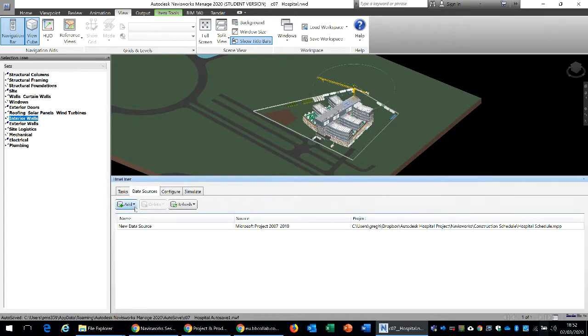So you could bring the bar chart or your plan, which is developed in dedicated scheduling software, within this environment. Your plan could have been developed in Primavera or Microsoft Project, or you could use any other scheduling software, and then you can export your plan into a CSV format, a comma separated format, and then import it within this. So this is one way through which you can generate a bar chart, and then you could link it.